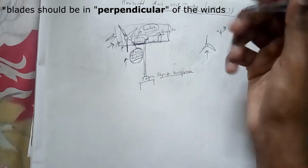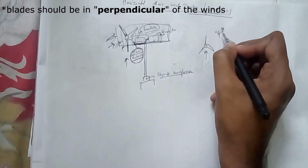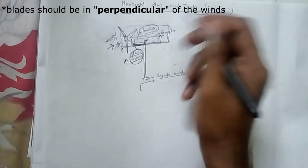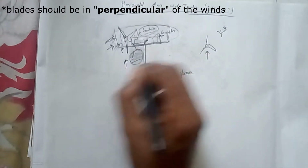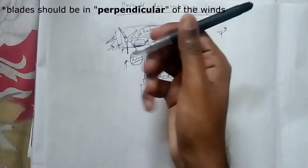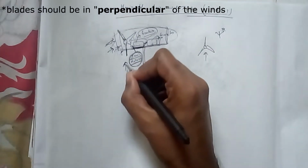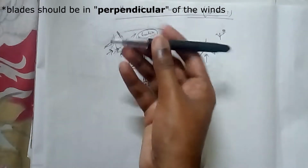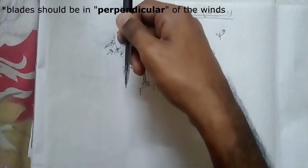When it sees that wind is coming from a different direction, it tells the yaw mechanism, and the yaw motors turn this whole structure into the parallel direction of the wind. So suppose wind is coming from this direction, then these blades will turn parallel to the wind.